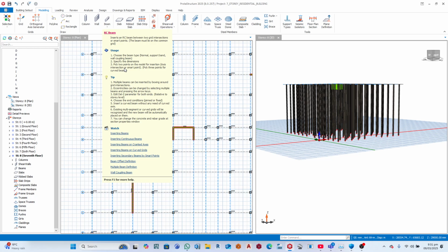So even when you click the generate, there will always be some extra steel. So this one gives you an opportunity to just analyze the column as one continuous member from the top all the way to the bottom without it interfering with other columns. When you do generate, you are saying there's a different column from the 6th floor to the 7th floor, and there's a different column from the 7th floor to the 8th floor.